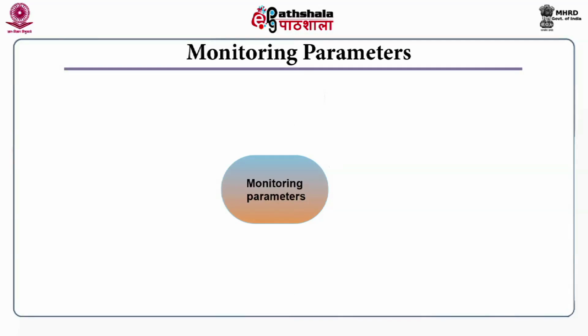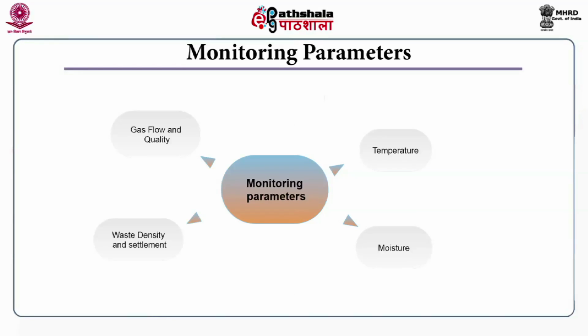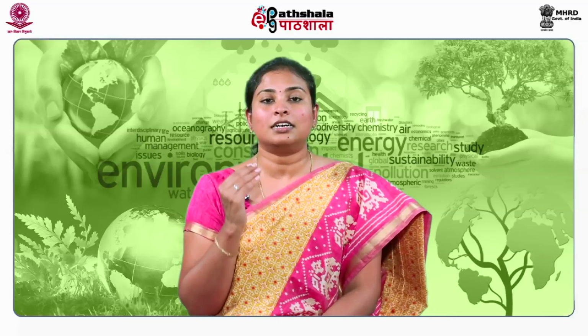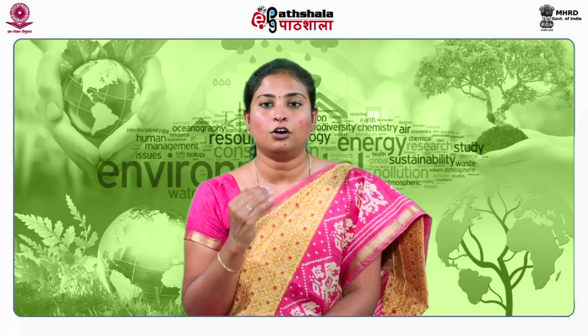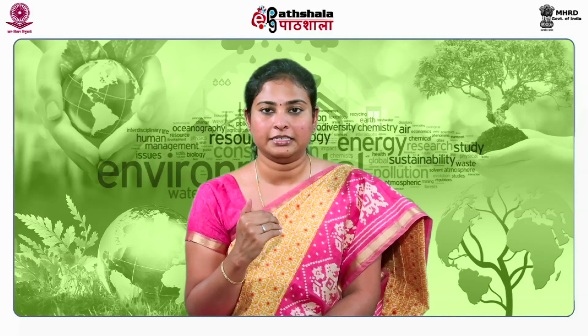Now, let us discuss the various monitoring parameters to facilitate faster waste degradation in the landfill bioreactor. The different monitoring parameters are moisture, temperature, gas flow and quality, waste density and settlement, leachate yield and quality, and leachate flux. Continuous monitoring should be done for the landfill bioreactors so that operational failures can be minimized.